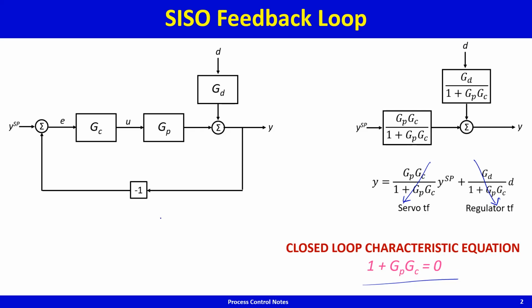and if you look at a PID controller with the D action in there, you will see that in terms of deviation variables, so there's no bias term, u is Kc times e plus 1 by tau I times the integral of error till current time plus tau d times the derivative of error.